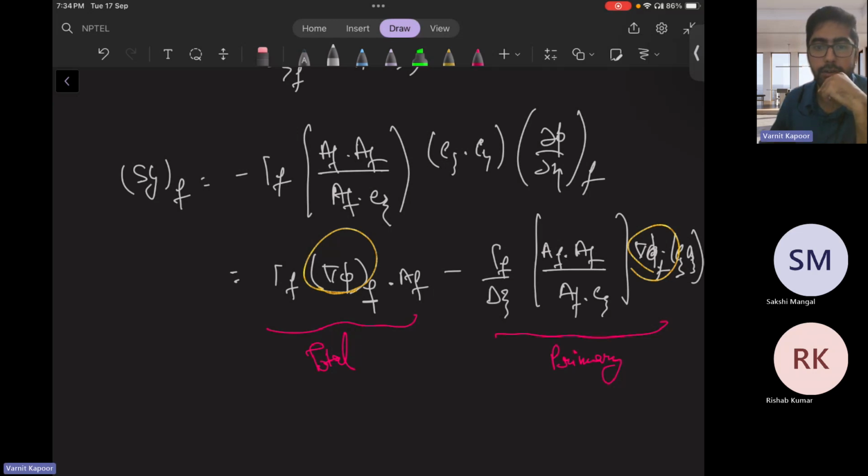So if you have a calculation of secondary gradient for an unstructured non-orthogonal mesh, it is a good idea to make use of this structure and calculate the secondary gradient from A, B, or ABCD values. But in your own codes, if you have some structured mesh, for 3-dimensional, or if you are 2-dimensional structured or unstructured, it is good that you start with the previous methods that we have discussed.